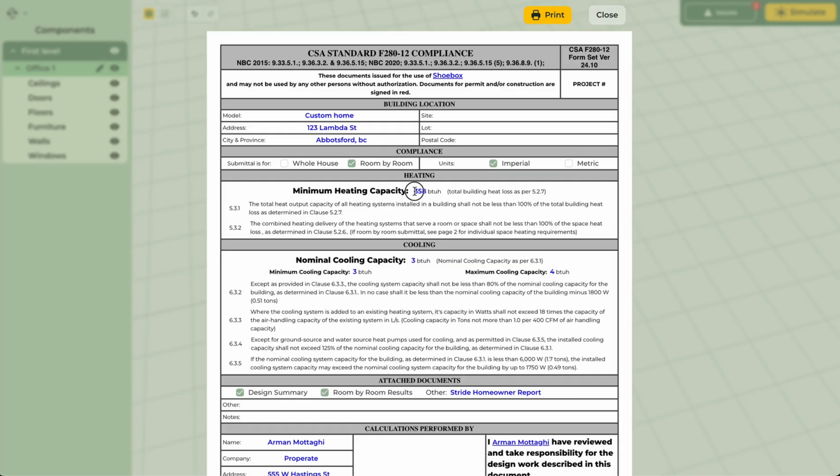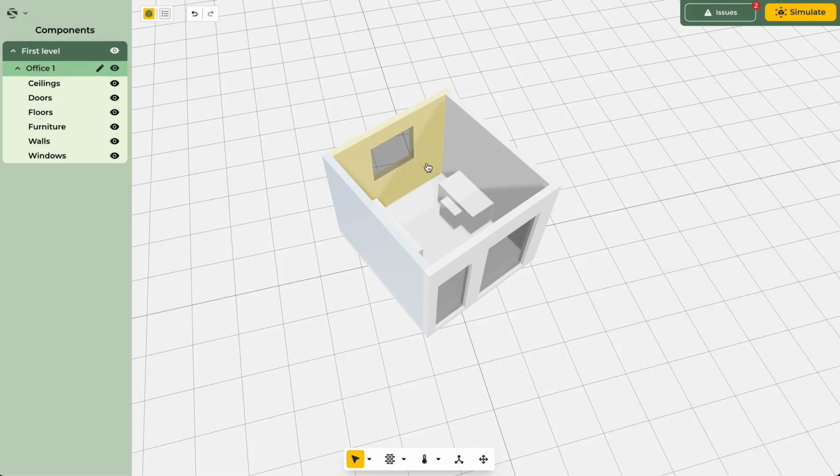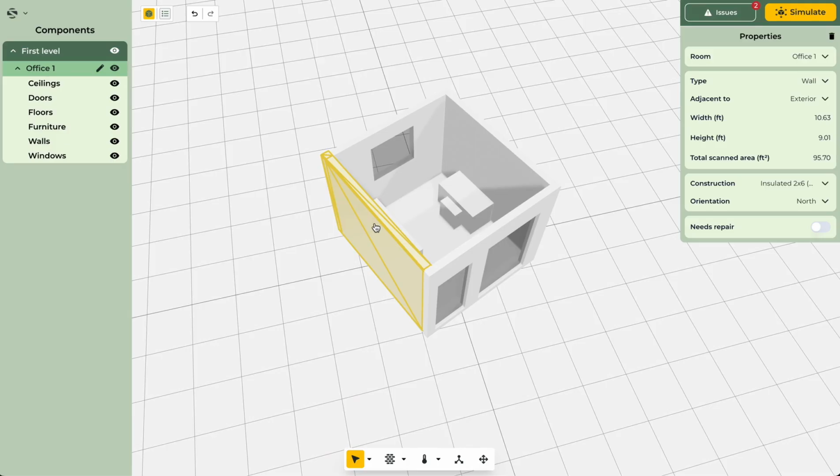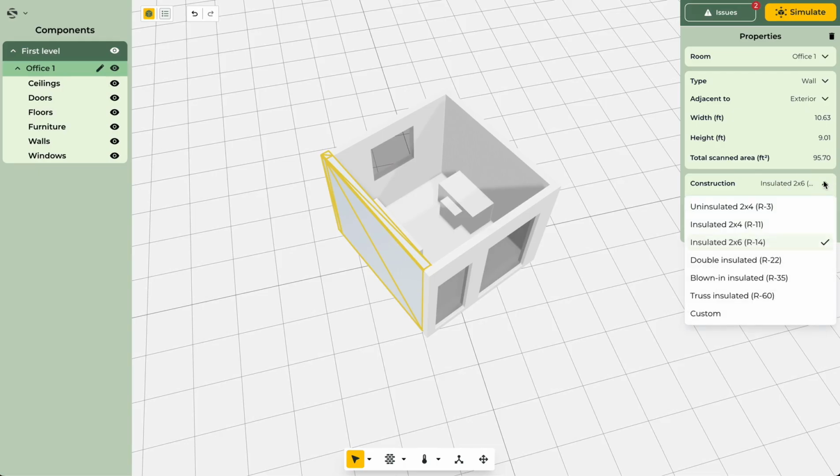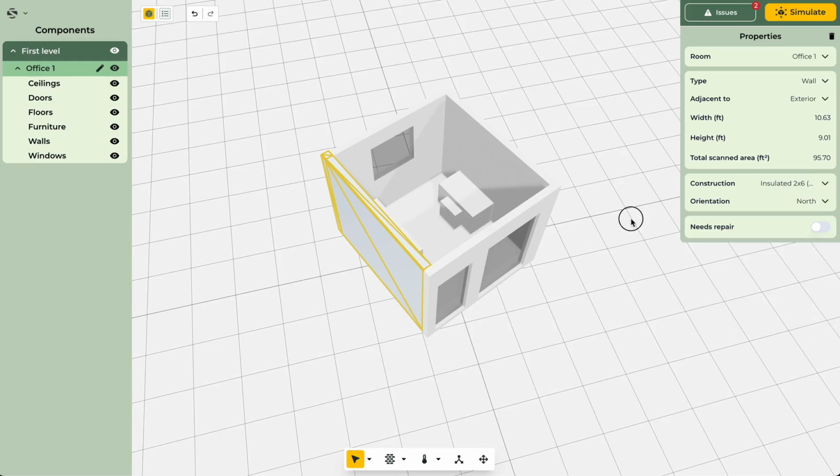And you will notice that our number here is 358 for heating capacity and a very small number for our cooling capacity. Now, if I select this wall, I will see the parameters of area of this wall and this R value, and I can understand that these components are generating that 358 BTU. But we can go one step further than that, and we can actually calculate by hand manually for this one wall, which is a simple north-facing wall, where that number is actually coming from.